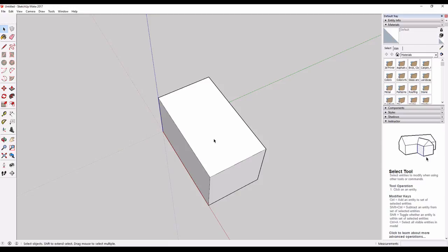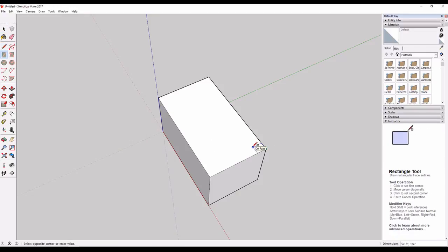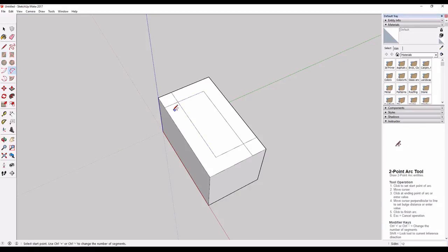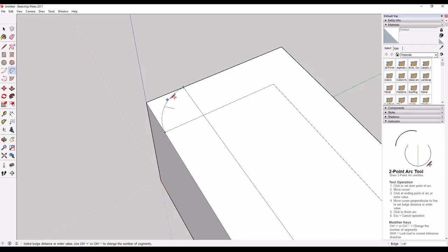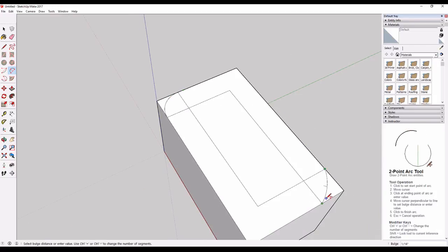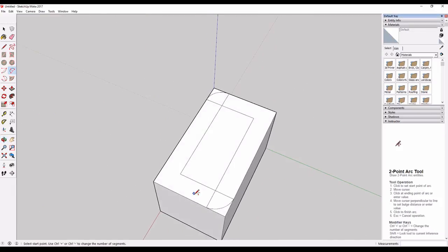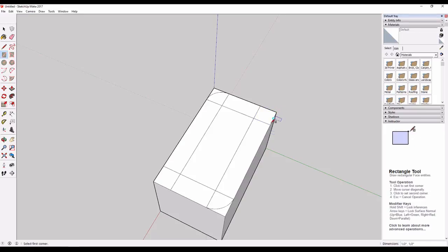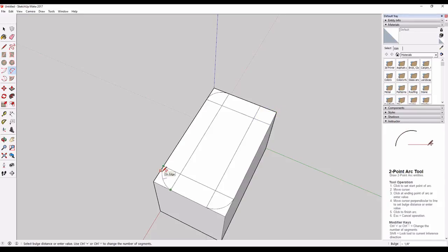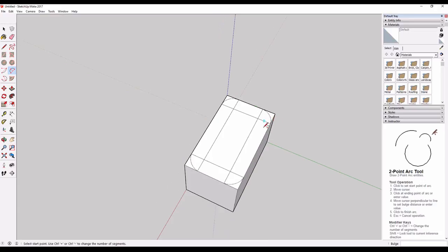Using the drawing tools listed before, create 2 opposing squares at 0.5 inches as guides. Hit R to connect them with a rectangle in between. Before you delete the guides, hit A to form an arc between the opposing guide corners. In this case, key in 1/8 for the radius. Recreate these arcs on the last two corners.